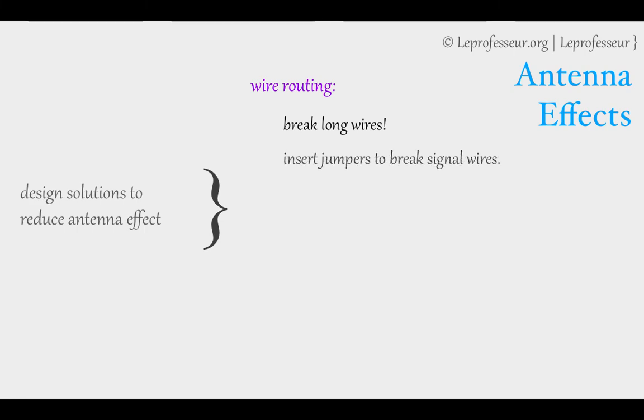And how to break? A technique called insert jumpers. Insert jumpers near the gate. And jumpers are nothing but the metal connections. Break the wire and connect at some other layer via the contacts.